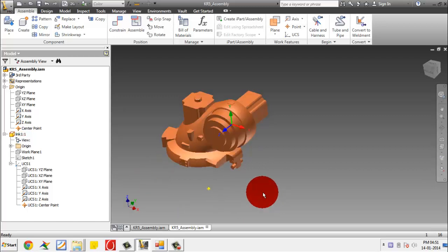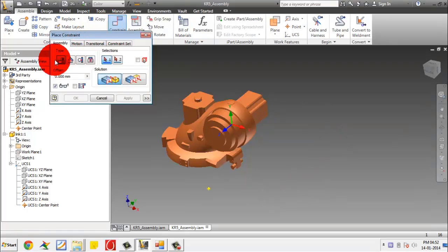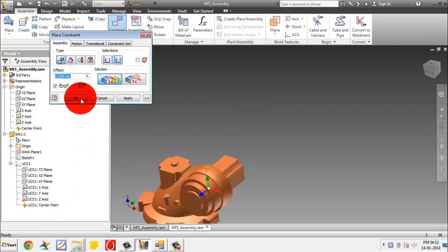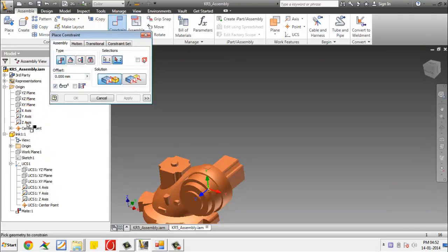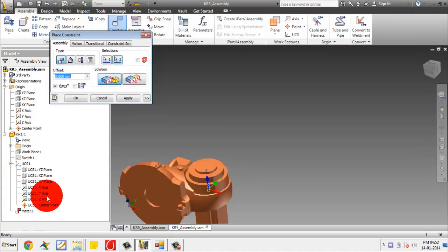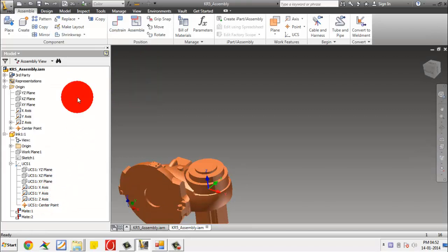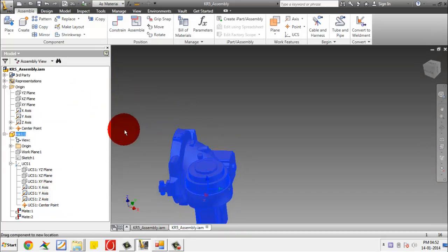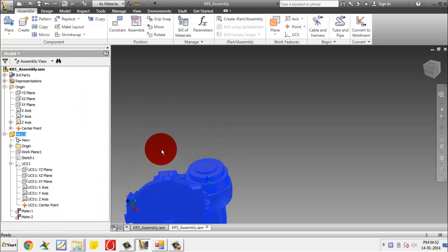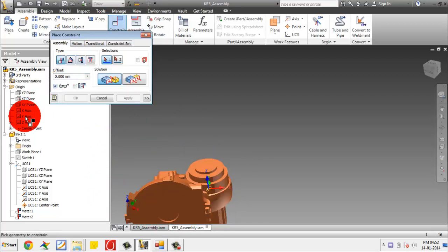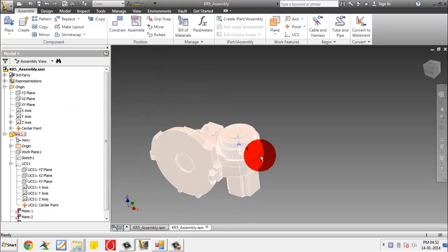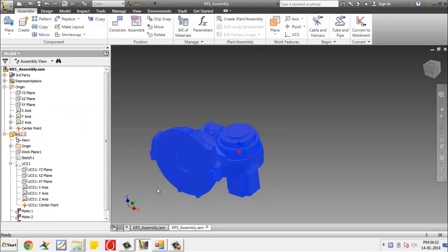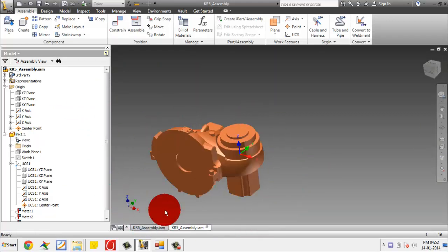So we can begin by coinciding the origins. Click on constraint, mate, click on the 2 center points. You can see they have coincided. Click on OK. Again constraint. Now we can coincide the z-axis of both the frames. See, the z-axes have coincided. Now if you coincide, it still rotates about the z-axis, so we need to constrain one more axis. Let's coincide, say, the y-axis. So right now the link has been fixed and its UCS coincides with the origin of the inertial frame.